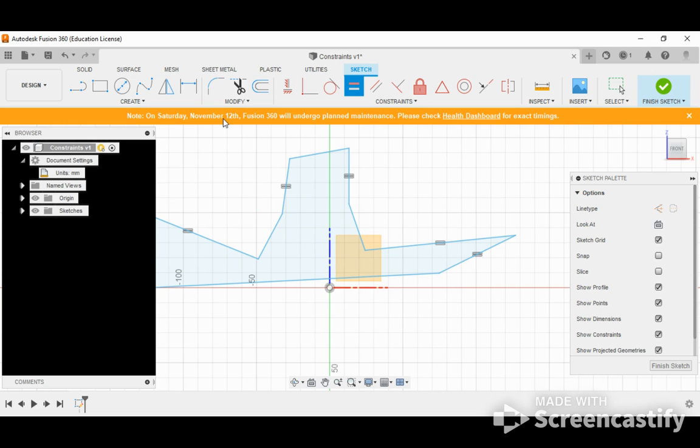Okay, well, that's interesting. We also want this thing to be centered. So I like to do equal, and I like to do your vertical, horizontal, and your perpendiculars next. So horizontal, vertical. This one. This will automatically choose whether it needs to be vertical or horizontal based on how close it is to one or the other. If it's wrong, you have to delete that constraint and shift something before you can try it again. So I'm going to say that needs to be horizontal.